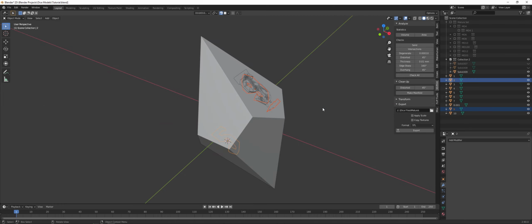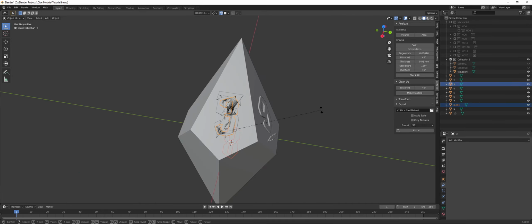You select 2, rotate, this time it's going to be Y, because it's the one aligned with the dice, and you do 72, because it has 5 faces and 360 divided by 5 is 72. So 72, then the next one is going to be Y 144.